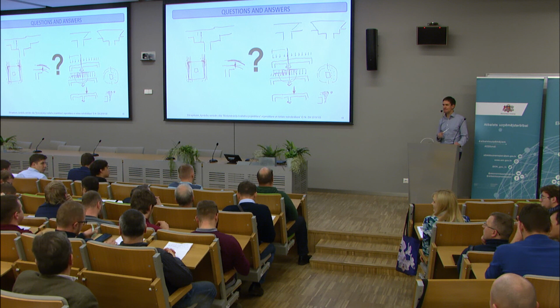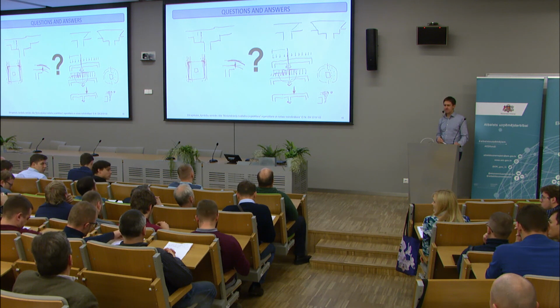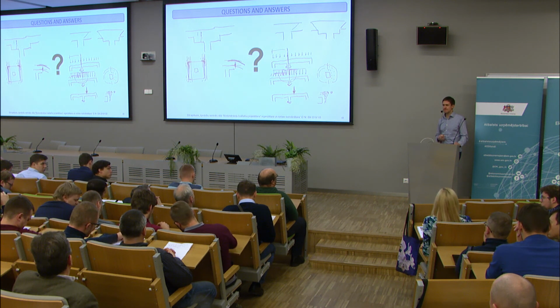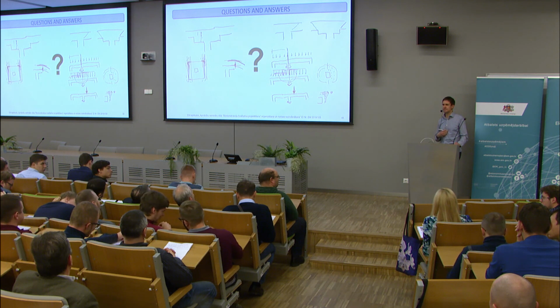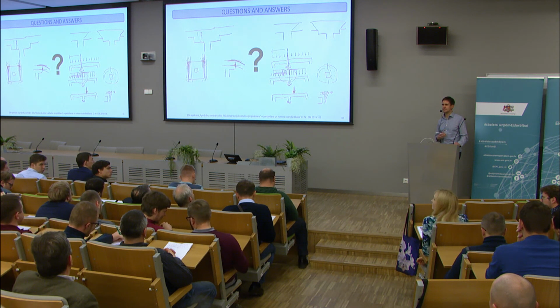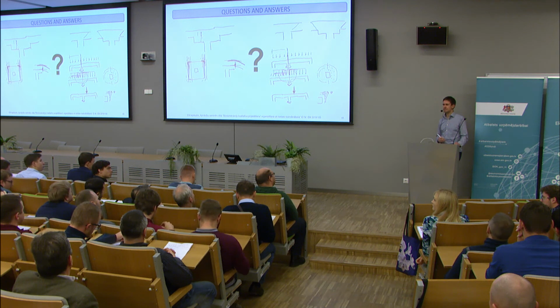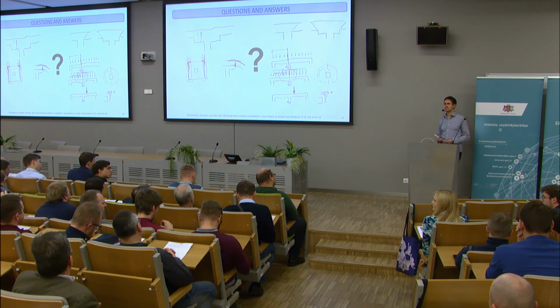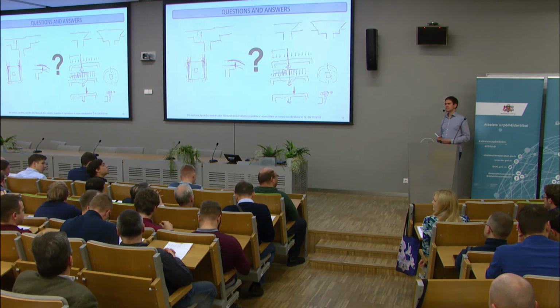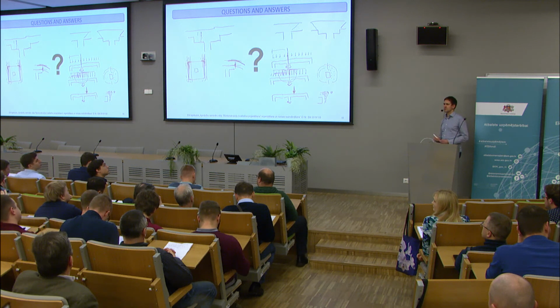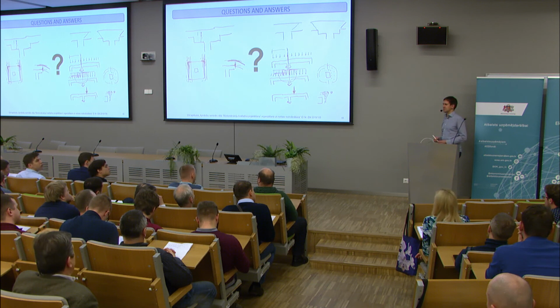For example, when you calculate a slab using the strip method, manual calculation, and then you calculate this slab using FEM design computing, do you get any difference in the amount of reinforcement? For example, using the strip method, you get more reinforcement than using FEM design.